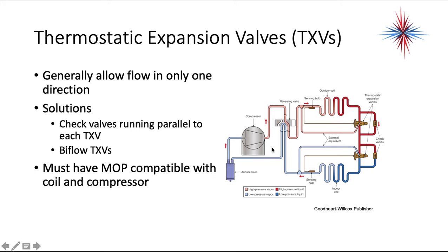So if we look at the diagram here, we will see how this works. This system is in the cooling mode. So we're sending our discharge gas from the compressor through our outdoor coil. It is not going through the TXV. It is going through the check valve.